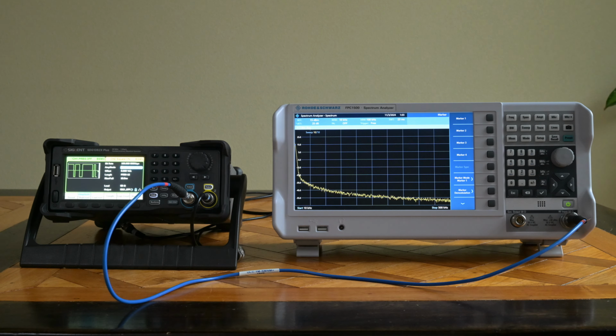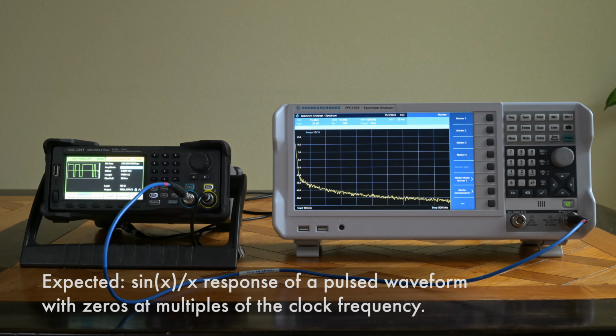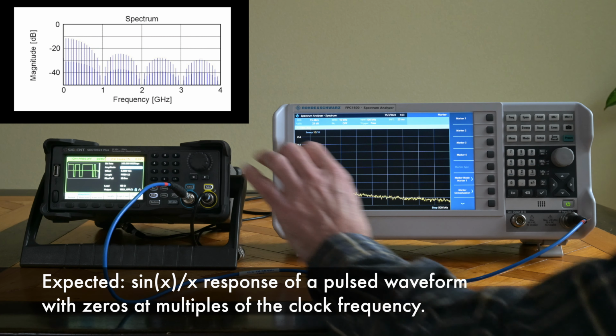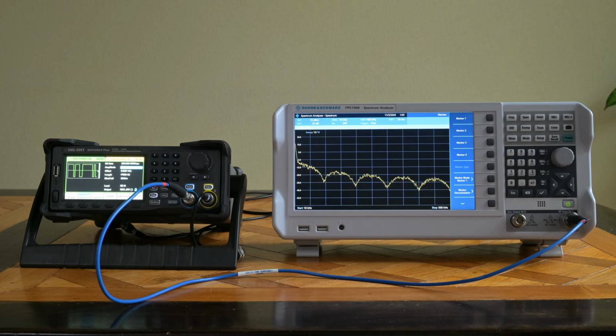In the beginning of the video I also said something about the spectral properties of a good PRBS signal. So I'm also going to take a quick look at that. I set it up here with a spectrum analyzer, and we should be expecting a sine x over x response for a pulsed waveform, and also with zeros at the multiples of the clock frequency. Clock frequency is 100 kilohertz still. Going to turn it on here.